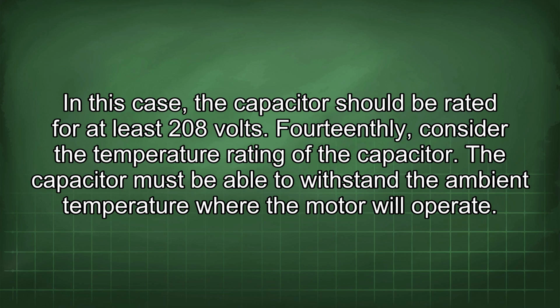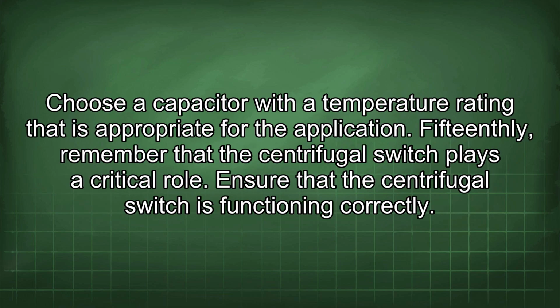14th, consider the temperature rating of the capacitor. The capacitor must be able to withstand the ambient temperature where the motor will operate. Choose a capacitor with a temperature rating that is appropriate for the application.